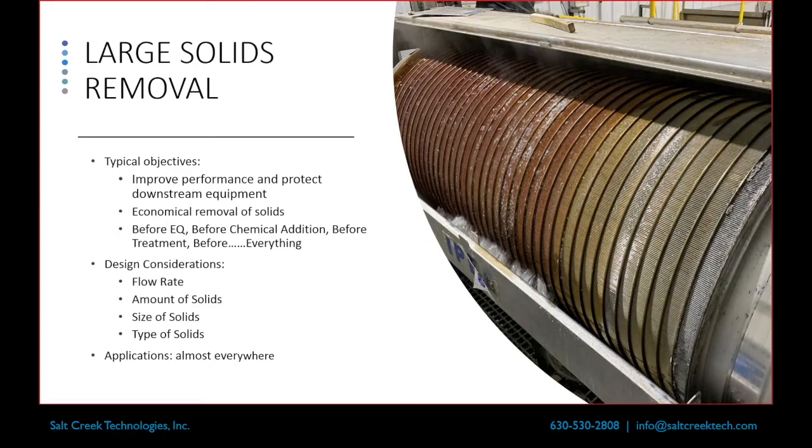We run into a lot of problems with this actually. I think it'd be pretty simple, but it's not the flow rate, your average flow that you're getting through your system. When we're sizing a screen, I don't want to hear how many gallons it's putting through in a day. That's not useful for a screen. You want to know what your peak flow is.